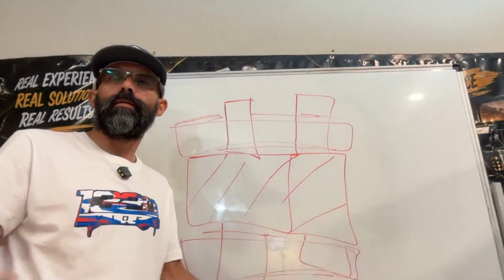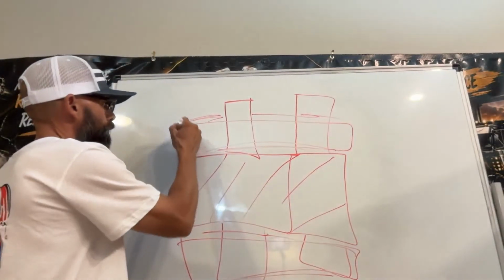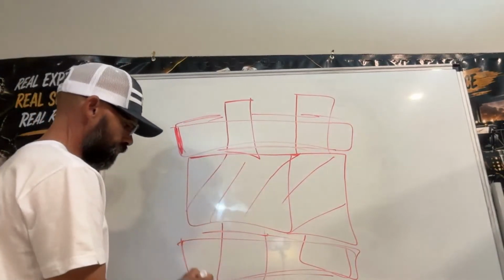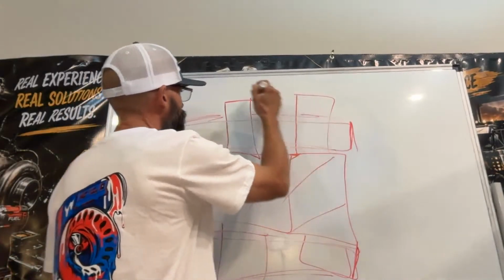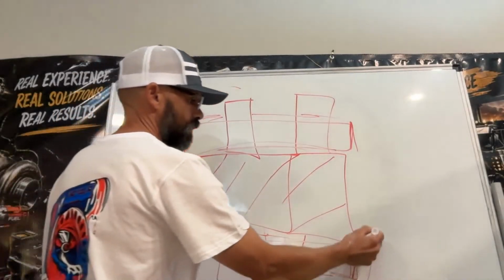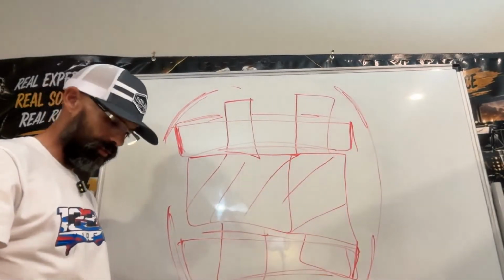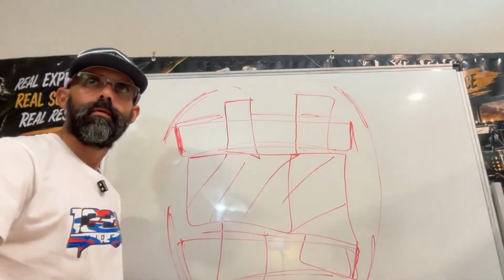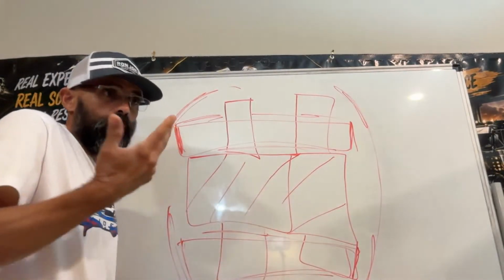Of course, you're gonna have the same issue because this plate over here is already worn out, also from the previous housing, and you're still having leakage around here. Of course, you're gonna have the same issue. That's why I say I would toss away the pump.